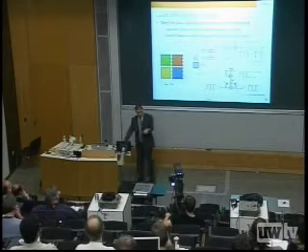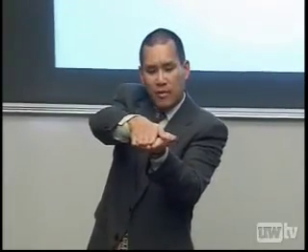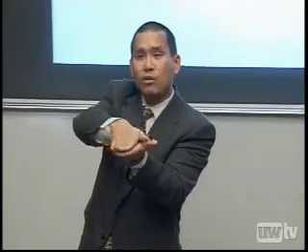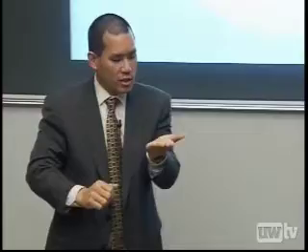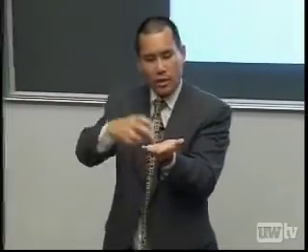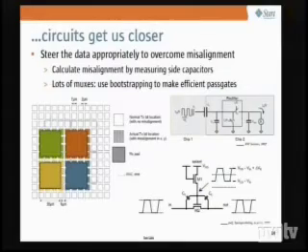Now, let's imagine I've got 2 chips with pads on the chips, and they're on top of each other and perfectly aligned. What happens if I misalign in a planar sense, so in X or in Y or in rotation? Well, suppose the transmit pads and the receive pads were not the same size. Suppose the transmit pads were actually made up of much smaller pads arrayed out appropriately. So let's pretend that these small pads were all transmit pads and the big pads were receive pads. When you put them together, the receive pads will cast a shadow on some set of the transmit pads.